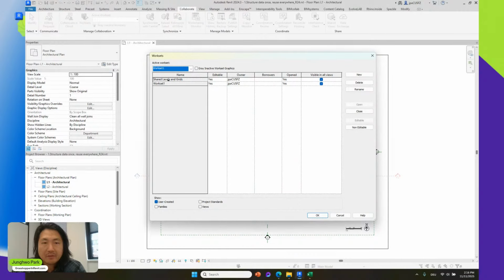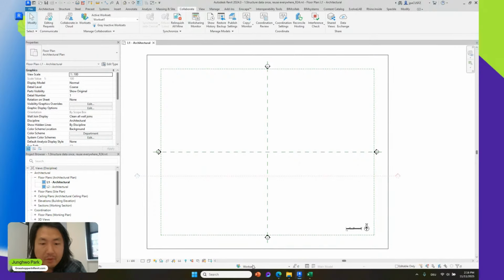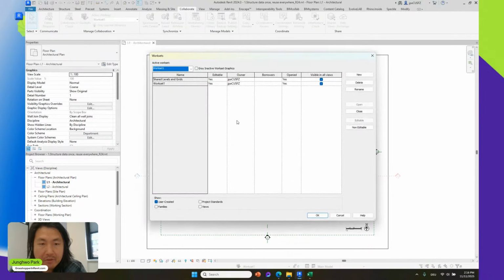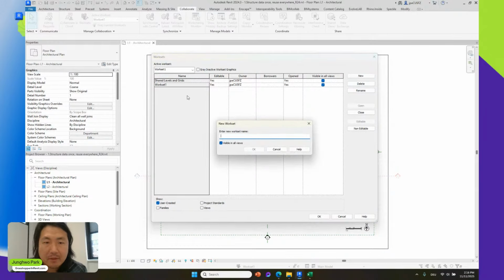And as you can see, we have here the list of worksets which we can create. So when I hit OK, then here we can set the major workset, and we can also browse that workset table. I know maybe some of you may never have used worksets or set them before, but this is a typical manual process.